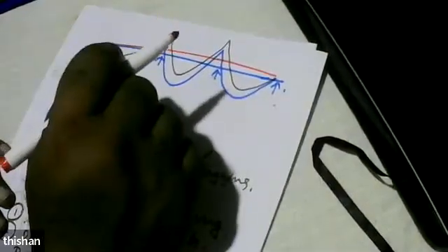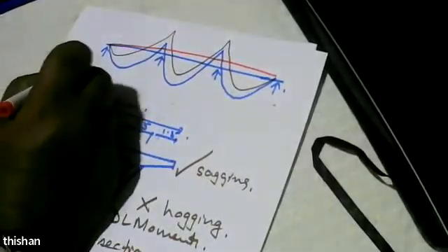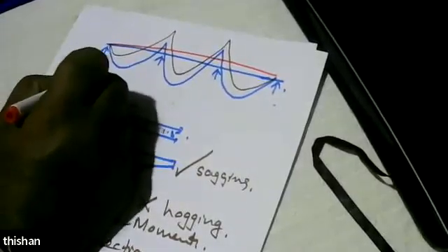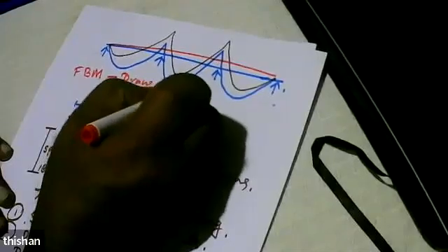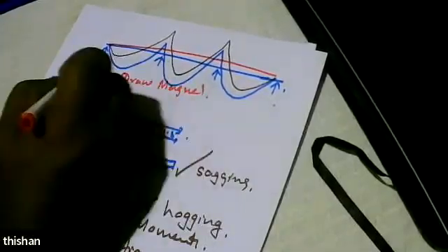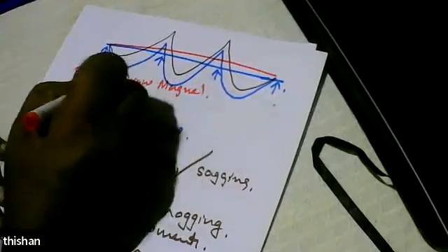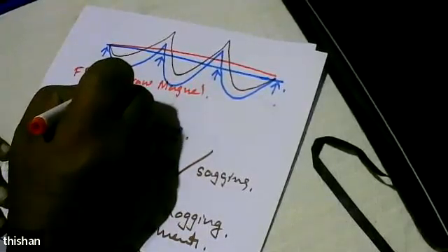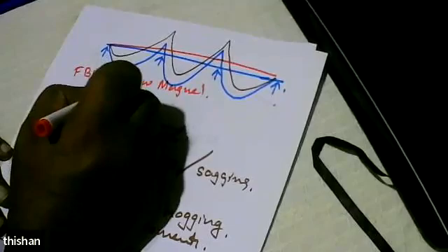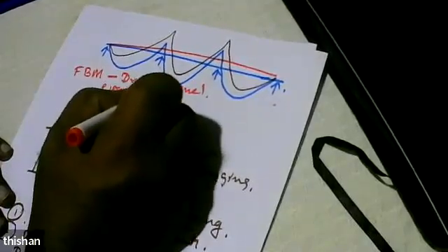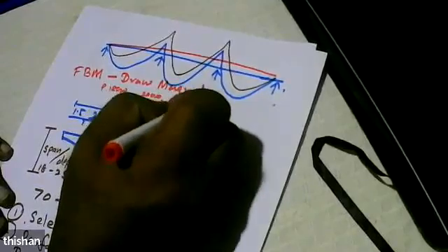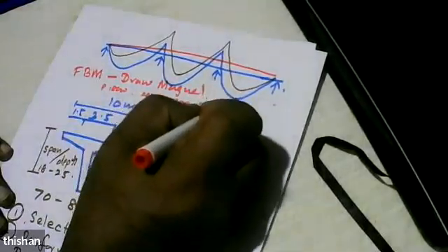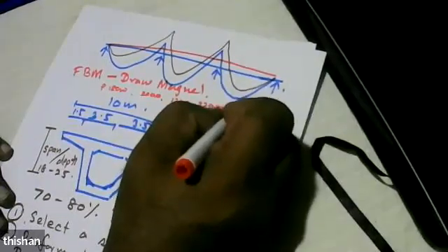Because now we have already got the secondary moment in, that's the final bending moment diagram. For the final bending moment diagram, we draw Magnel diagrams and find P. So P might be 18,000 here, and it may be 20,000 here, and 70,000 here, 22,000 here, 15,000 here.